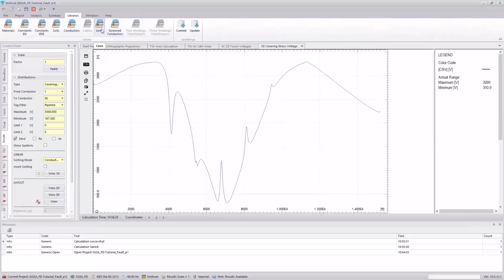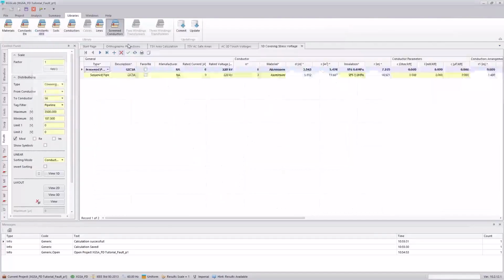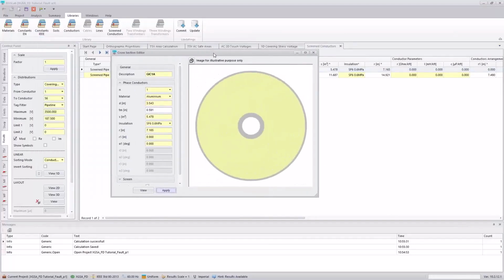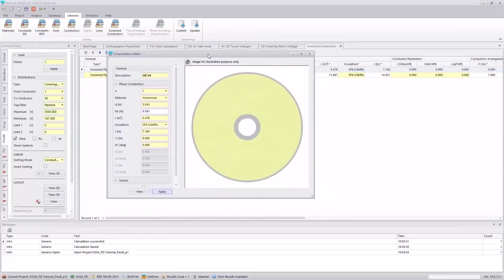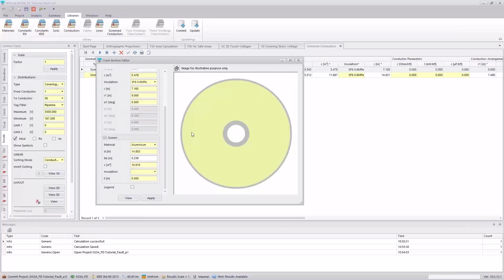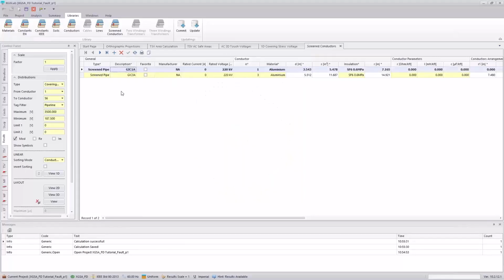One thing I do want to highlight, that question brings up, is these screened conductors, which are one methodology for modeling both gas insulated switchgear or busing, as well as cables. So you can add insulation on the exterior of this to pretty much create a cable in the model. So the software itself is pretty flexible. Whatever you have in the real world, you can model in the software and approximate what the electromagnetic effects are going to be for that.